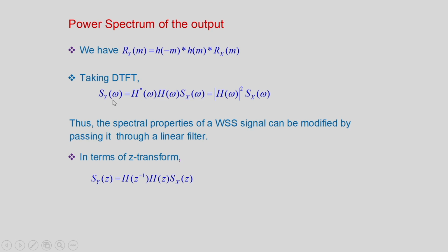This power spectrum we can also express in terms of the Z transform. So, Sy(z) will be equal to H(z^-1) into H(z) into Sx(z). This Sy(z) is the generalized PSD of the output process, Sx(z) is the generalized PSD of the input process. We will consider one example.